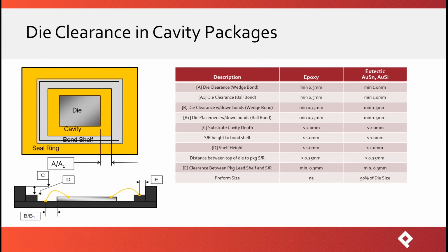Here you'll see that basically 750 microns is pretty, if you will, generous. In essence, we generally can go down to 350 micron as far as that goes. But again, there are some other details regarding the die placement and the die flag, or basically the size of the pad that we're putting the die on. It's not uncommon that we sometimes even put die larger than the die attach pad area for certain cases. Or in the case of our OCPP product, we actually make the die attach pad area larger than the original package.